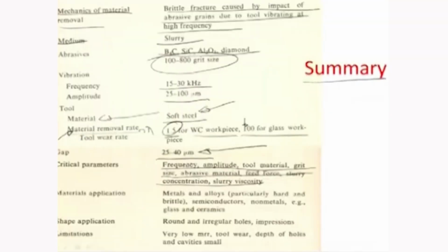It's a low yield process, high tool wear, and of course you have a limitation in terms of depth of cavity or the depth of holes that you can realize, although in microsystems that is an advantage because the cavity that you are looking at actually is close to some tens of microns in thickness. And so this process is very well used in microsystems for doing active fabrication.